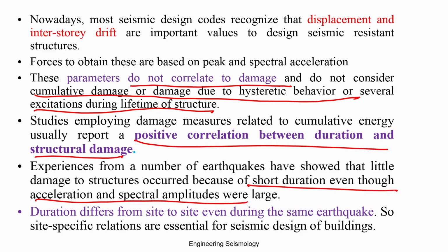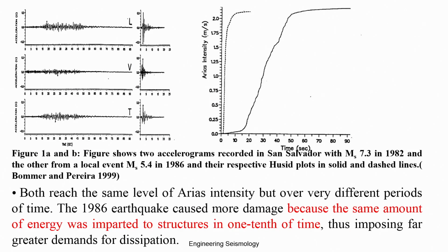The duration differs from site to site even during the same earthquake. Site-specific relations are essential for seismic design, as this duration is controlled by the path, source and site. All this information is included in the duration of the earthquake.